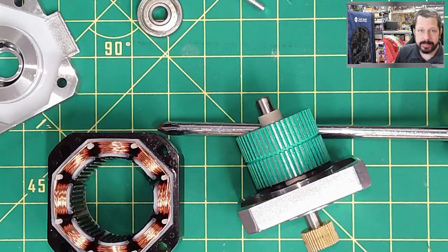Printers that do have that inertial mass needing to move back and forth, like they're slinging the bed back and forth, you're going to get ringing in your print if you try to print really fast. And some people really want to print fast. They want to get the part made quickly and move on to the next thing, but you're limited on a printer where the bed moves back and forth by just how fast you can move that bed.